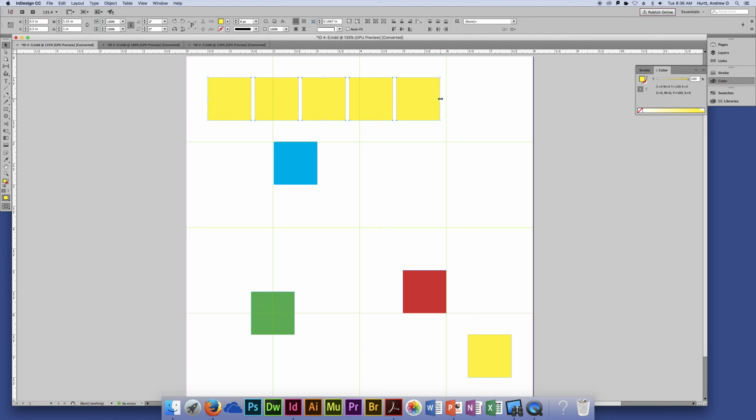So if you had, let's say, more space than you thought, and you wanted this to be more even with this margin, give or take, you can hold spacebar and drag, and that will keep the objects the same size, but it will also adjust that distribution with the objects. That's a super handy thing. I don't think that's in Illustrator. At least I've never seen it come up.